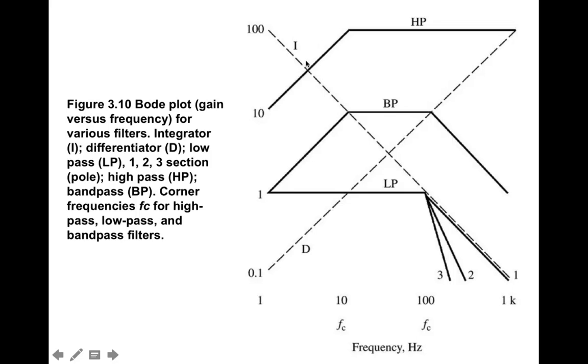So we can see that at low frequencies on a log scale, our output over input is decreasing. As frequency increases, our output over input becomes constant. So this is a high pass filter because the ratio of output over input is constant, usually 1, for higher frequencies. The low pass filter, notice, is flat at the lower frequencies, and then right at the cutoff frequency, you begin to reduce your output voltage over input voltage ratio. So it's cutting off or eliminating frequencies that are higher than this cutoff, shown at what looks like the upper knee of the curve.